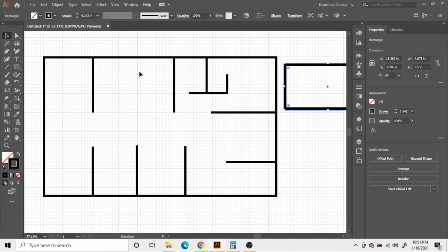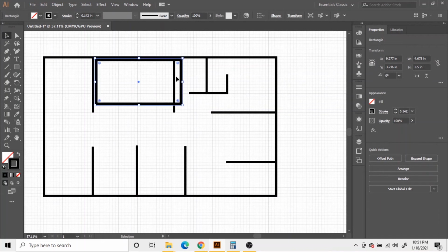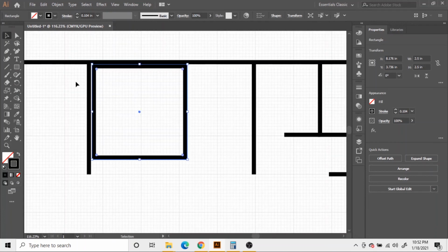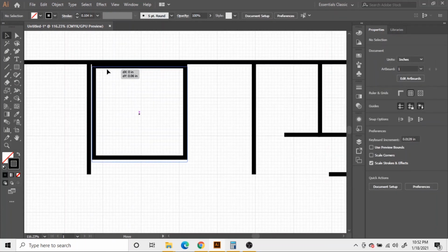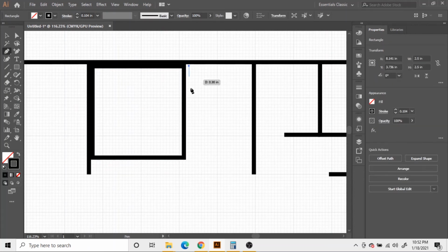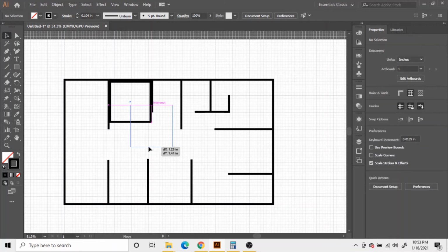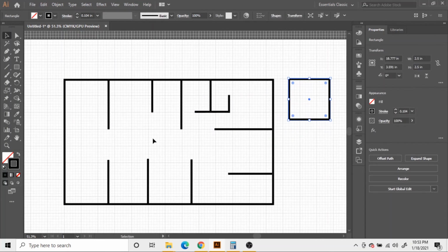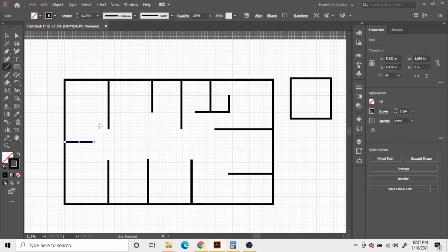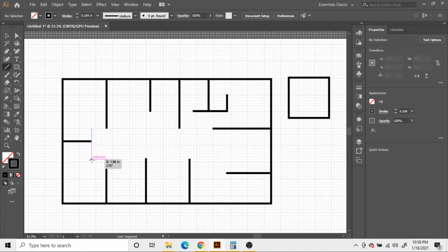Now let's set the dimensions of our dining room. Let's choose to make this 10 feet by 10 feet as well. So the scaled size of this room in this technical drawing will be 2.5 inch by 2.5 inch. Let's set our reference square inside the dining room precisely and let's create a vertical wall here. Now move this reference square out of this room and place it outside of our drawing. Let's draw a horizontal wall in the exact center here. Now draw a vertical wall like this.